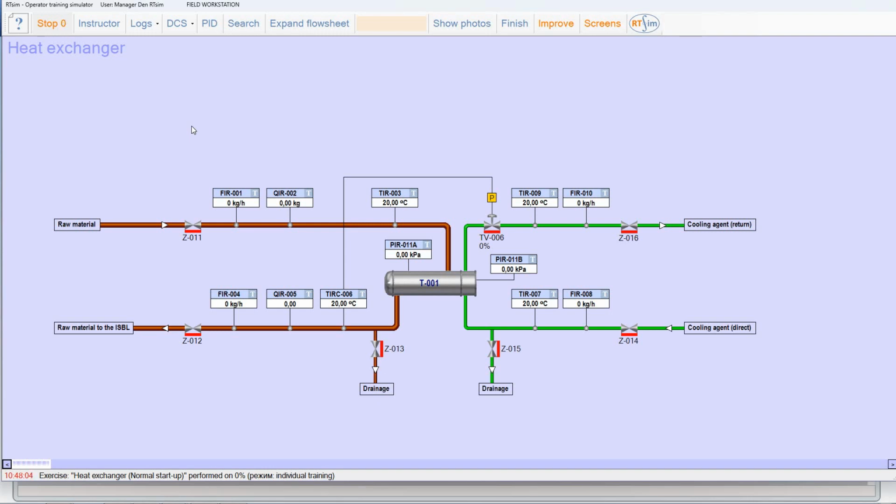So, the right answer is that this is done to avoid thermal deformation. Even though the temperature might not seem very high, if you start the heat exchanger from the hot side first, its tubes will warp and look like spaghetti. That's why, remember, you always need to start any heat exchanger only from the cold circuit.